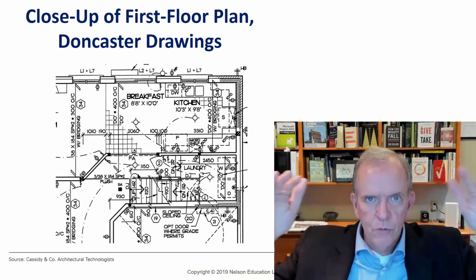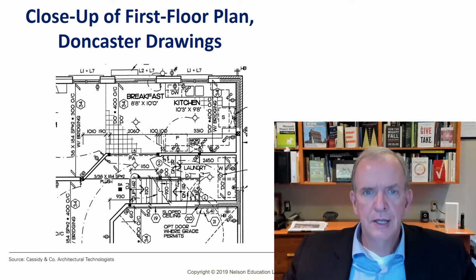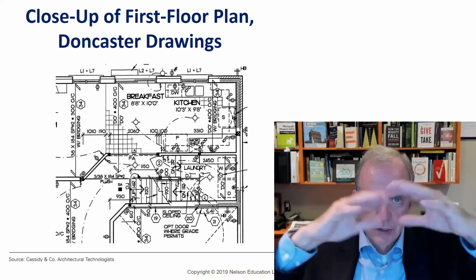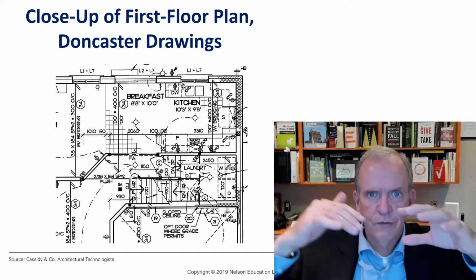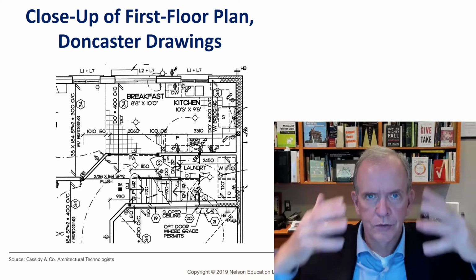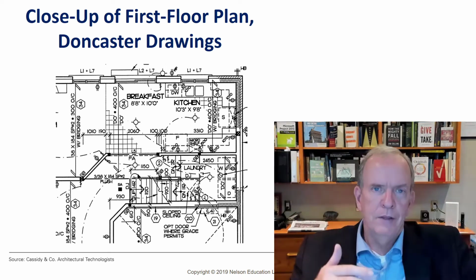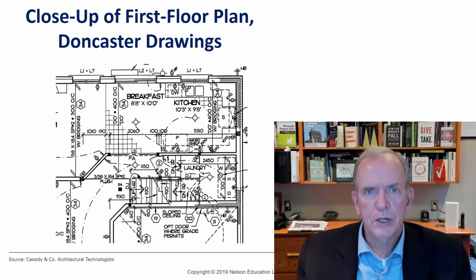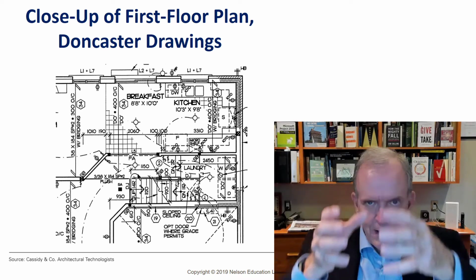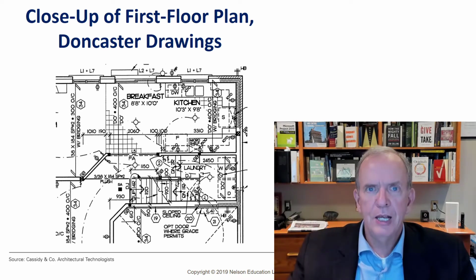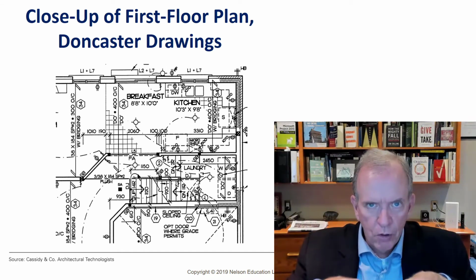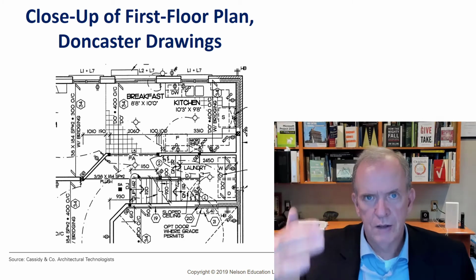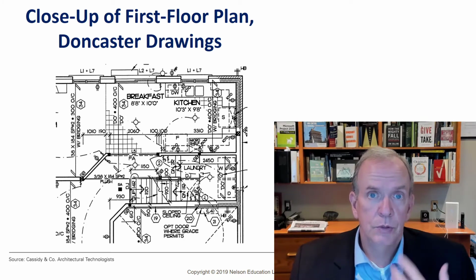You're always trying to think, how is the load transferring itself through the structure, right? And it's going from things like the roof, and the snow is transferring to the roof, and then that's transferring to the exterior walls, the load-bearing walls, through the trusses. And the trusses, if it's a girder truss, it's transferring that to the solid bearing, and that load's then going through the structure. It's being picked up by the next floor, going again through solid bearing, being picked up by the foundation wall, going through the foundation wall, hitting the footings, and transferring from the footings into the undisturbed soil. So we just kind of recapped the last few lectures with that little discussion.